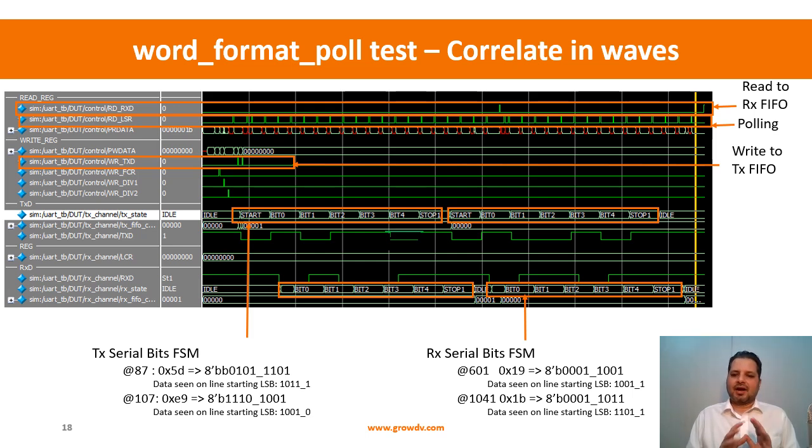So imagine we have done that process. We have looked at a simulation log file, understood the broad structure, identified a few important statements from the log file, and grepped them. Now we have come to the waveform to see whether what we have seen in the log file matches with the waveform. That is our current intent.